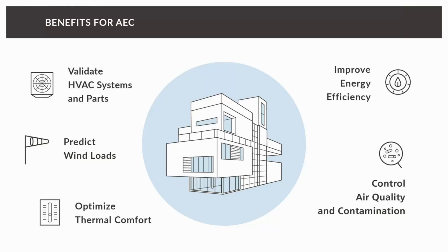For small buildings, you can use some tables, but for larger ones, you need to provide real test results. Usually people run wind tunnel tests with small scale models, which is super expensive. Using CFD, you can simulate the full scale model, including the surroundings, and it's much faster and much cheaper.